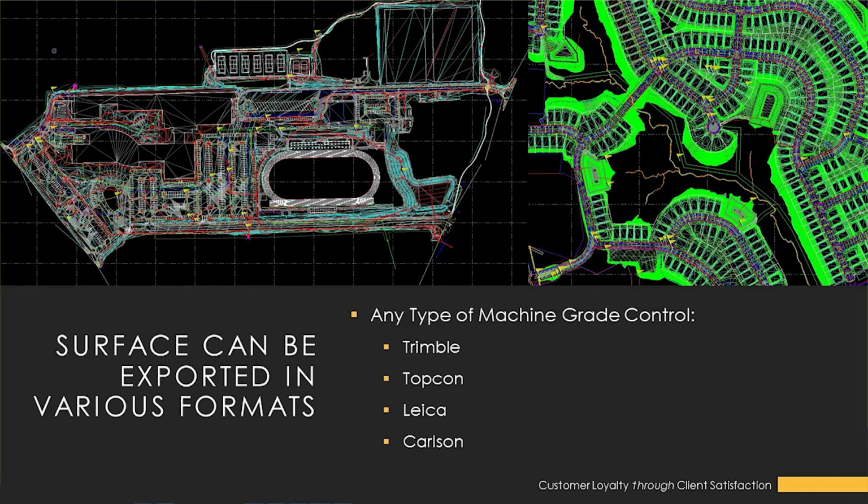Once all the necessary 3D polylines have been created, we can prepare the finished grade surface in the same manner as any typical topographic survey. This is typically done with a survey program or a civil engineering program such as Civil 3D or Carlson.